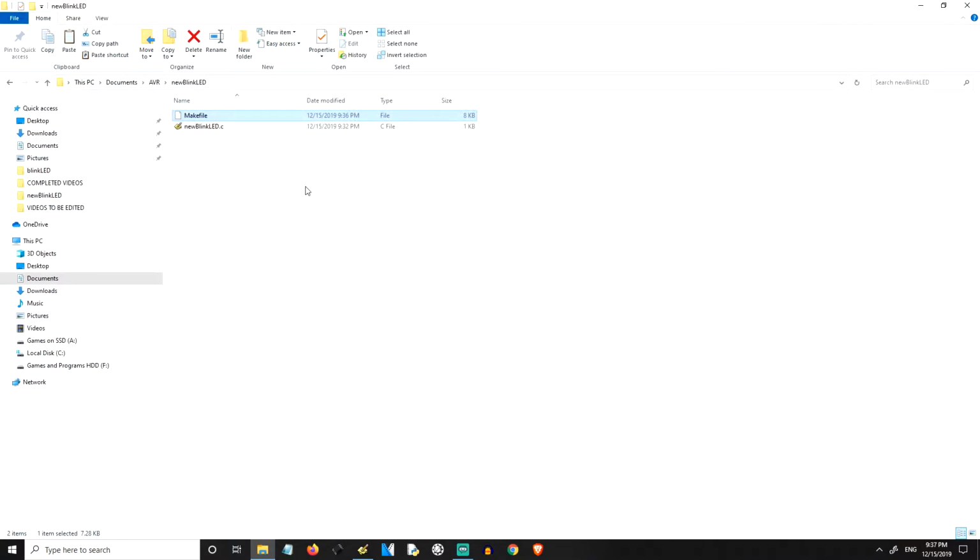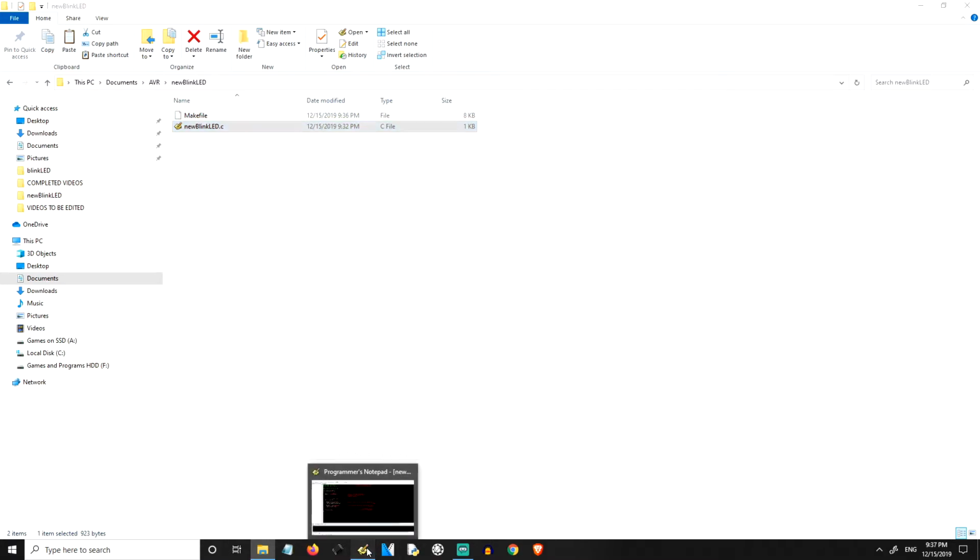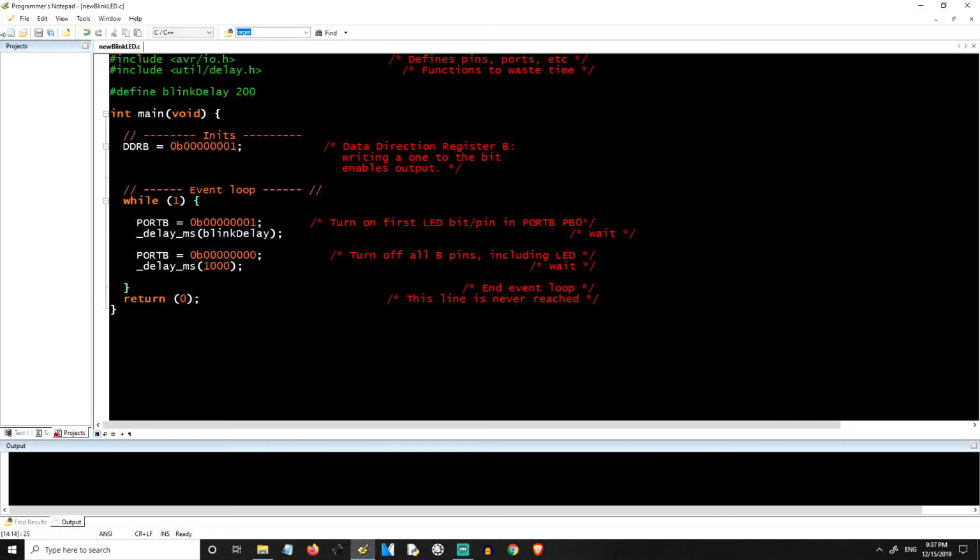All right, so that's saved. And we have our C file. So now you go back into Programmer's Notepad. In Programmer's Notepad, you're going to look at Tools. And here you're going to see it says WinAVR Make All. So watch this. When I make all, it's going to tell me if there's any errors. 0 errors. Okay, it took 1 second.